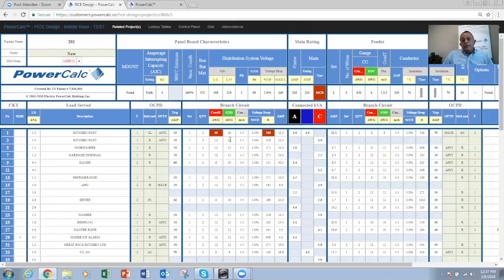Why do we have to perform the voltage drop? For maximum efficiency, each machine is designed to operate under a certain voltage. To get your maximum efficiency and maximum output from a machine, be within plus or minus, as the manufacturers say, 5 to 10% voltage drop. The optimum usage of that machine is at the rated voltage, so it will operate at optimum efficiency if you really provide that voltage.